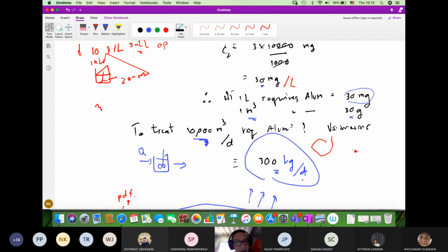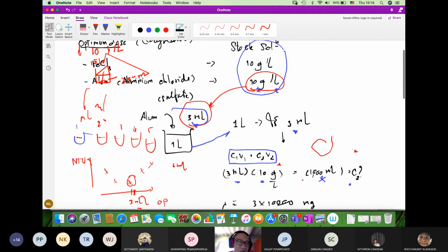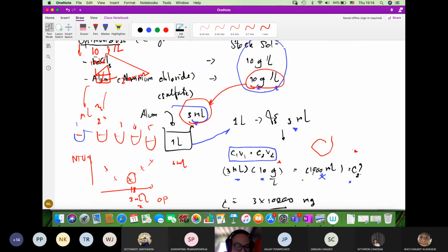So we determine the optimum dosage. So we need to prepare the chemical. We need to adjust the amount of the alums according to the results to obtain the lowest turbidity. Okay, so this is the beneficial use. So whenever you answer, you already get the optimum condition.